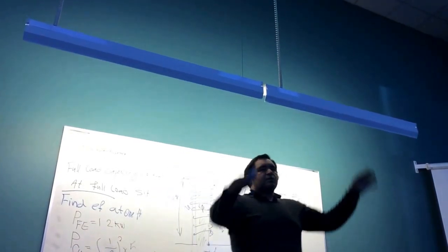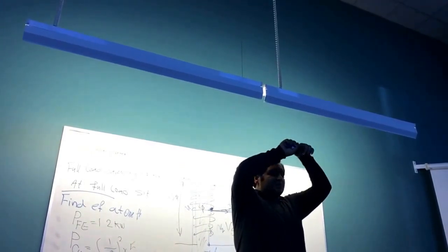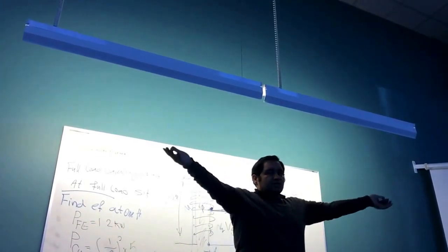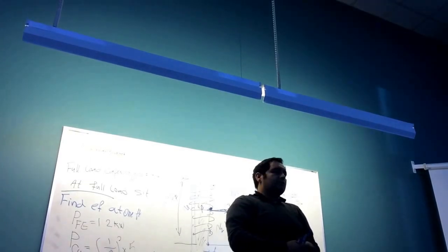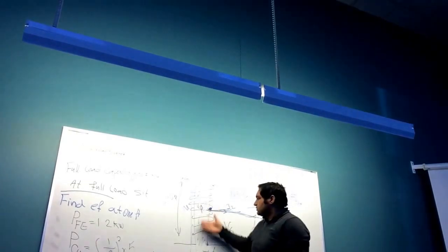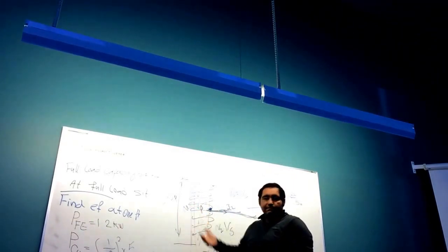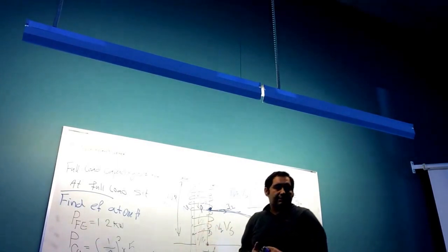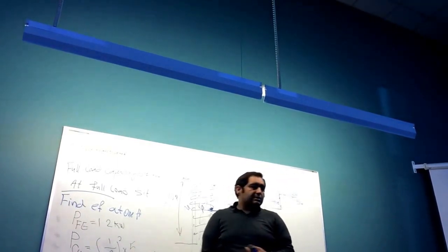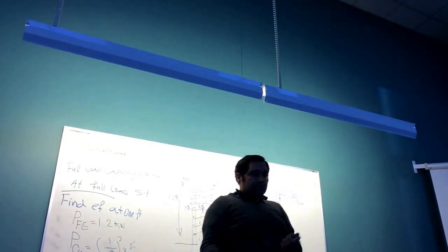And if the insulator is gone, what's going to happen, guys? Your transformer is dead, because it's just going to be a piece of copper. If all these windings stick together, then you don't have N. You just have a piece of copper, and your transformer is dead. So you need to have a system to get rid of the heat. Make sense? Yep.